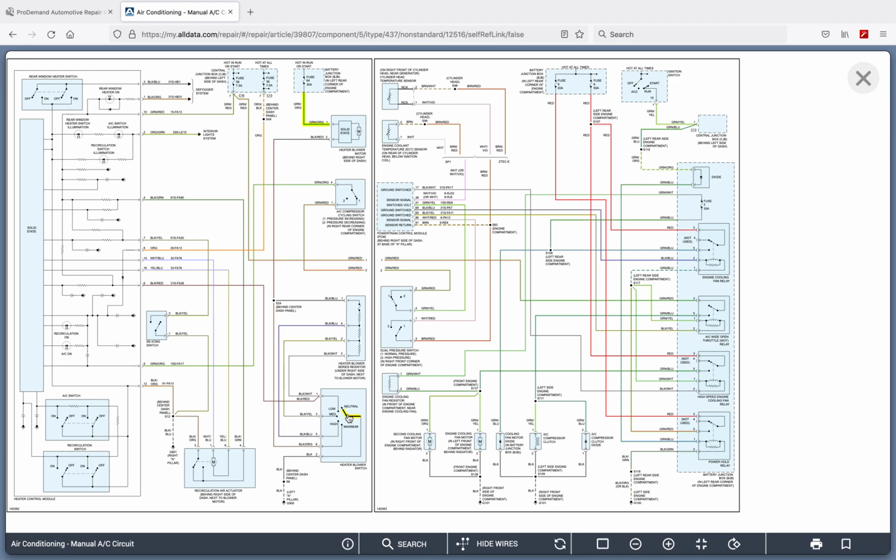Now if I get rid of that, I can go to the medium speed. Medium speed is going to be here. Now notice the manufacturer or the aftermarket redrew this diagram as an interactive map. So if this is my medium speed, I've bypassed a resistor. This is going to be my path of current flow in this layout. So we can see the benefit of using this type of service information that the aftermarket has redrawn.